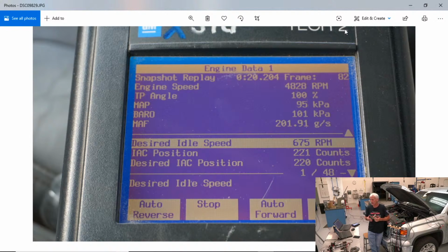You've got this displacement engine, 350 cubic inches, that for every 2 revolutions of the engine should move, at 100% VE, 350 cubic inches of air. It does not care about fuel, ignition, rich or lean, or spark advance.